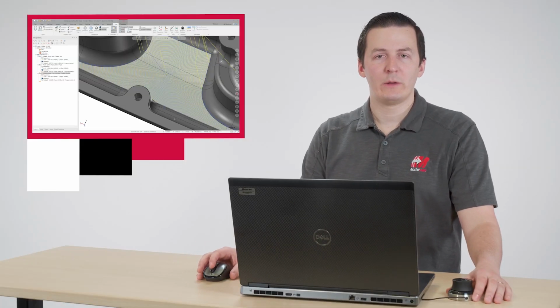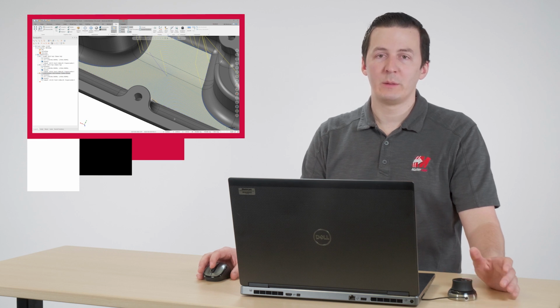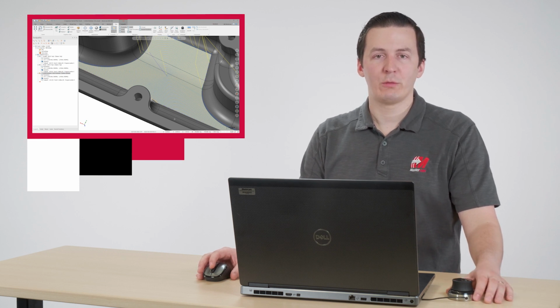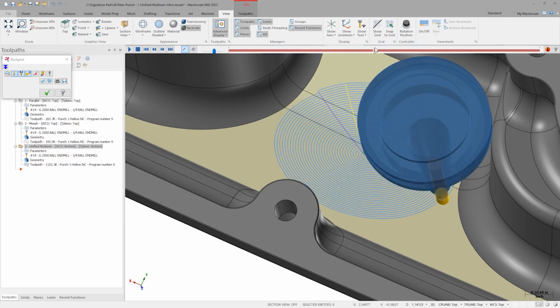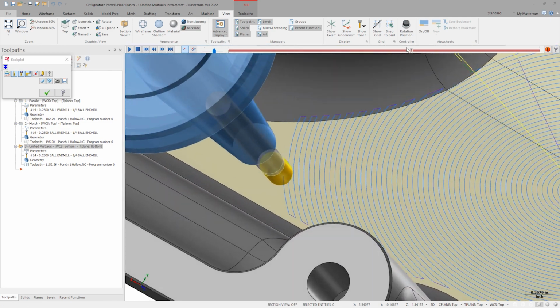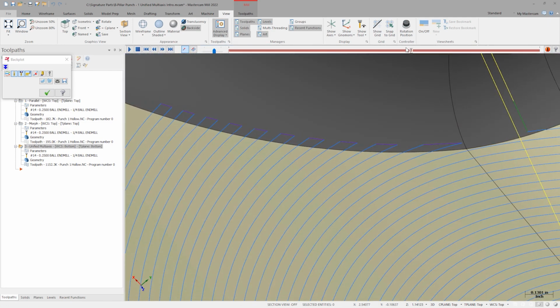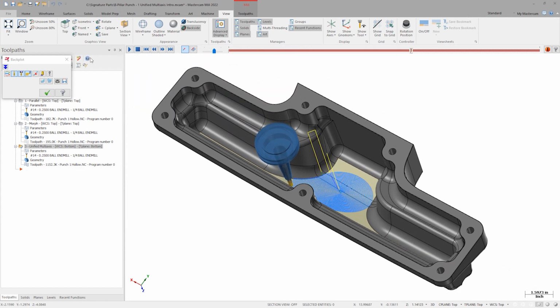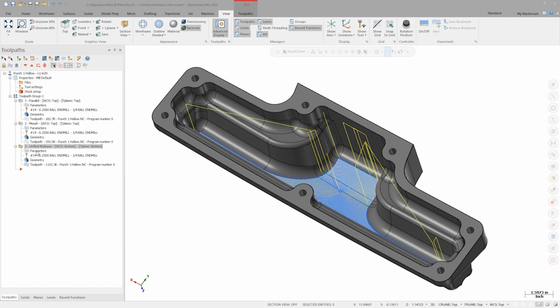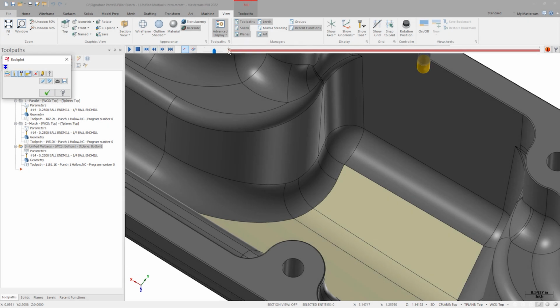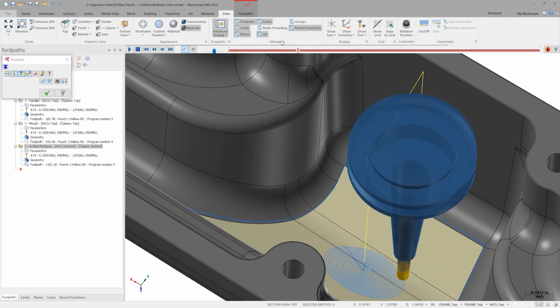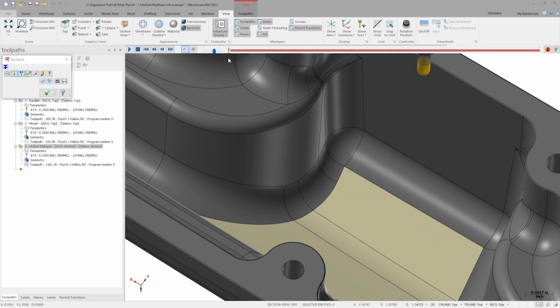Of course, there is a multitude of new options within the submenus of the Unified Toolpath, but there is one small, simple feature that can clean up the rough edges created by this particular cut pattern. Because there are some areas where a full step over can't fit on the machining geometry, many small cusps of stock will remain unmachined. If we open the Containment tab under Cut Pattern, we can activate Create Additional Cut from Containment and regenerate. These fringe areas are now machined by a single loop pass that runs on the outer edge of the machining geometry.